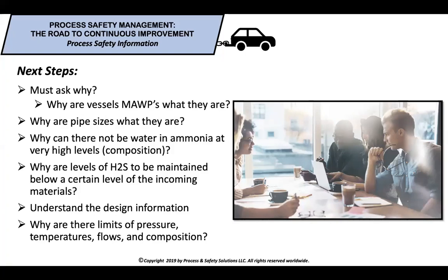As we looked further into the reasons why, we found that the engineer decided, to reduce some of the cost of an addition they were making, to go with 8-inch pipe versus the 12-inch. Unbeknownst to him, the reason it was 12-inch to begin with is because the inlet gas had a small amount of sand or silica in it, and that silica at a certain velocity would erode piping, and whenever it made changes in direction, elbows, etc., it would begin to erode that pipe away.